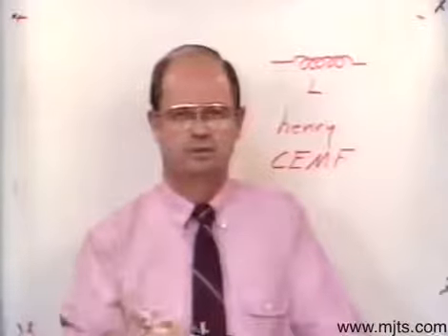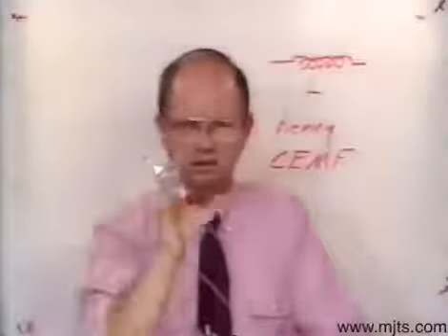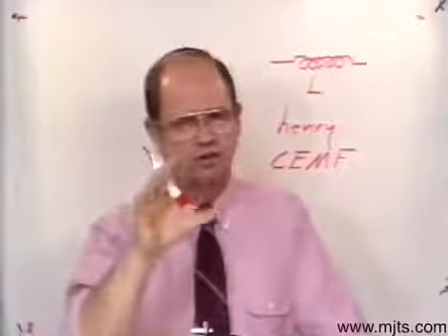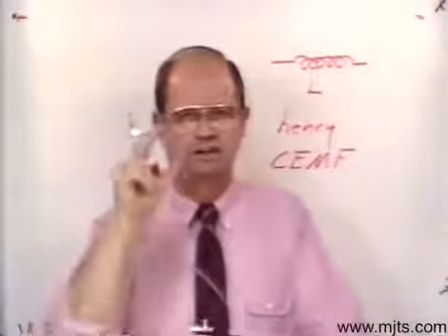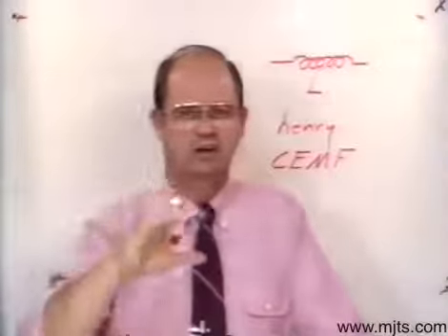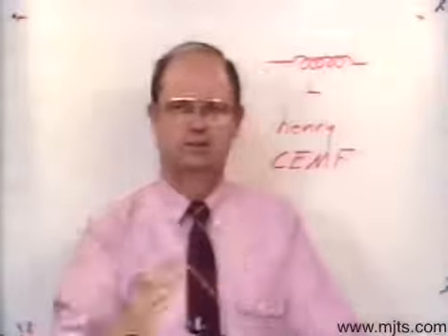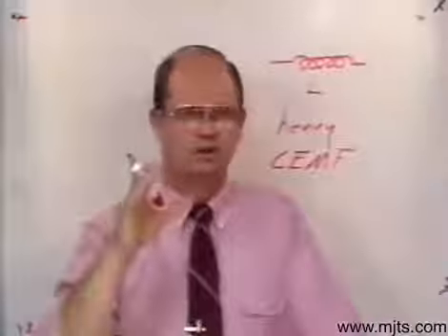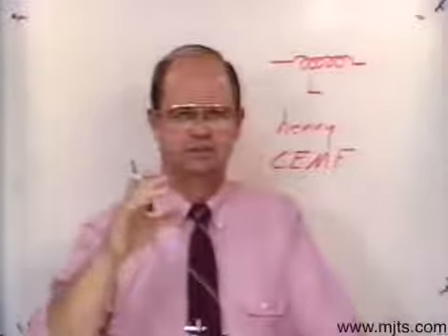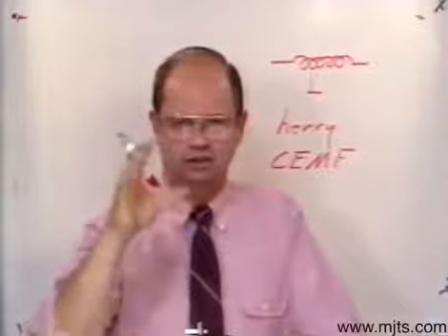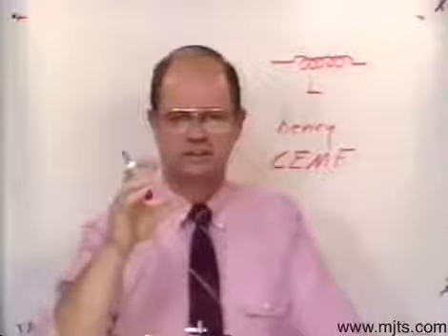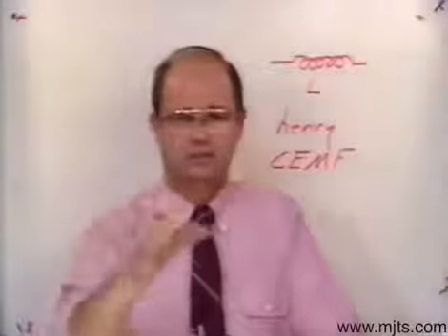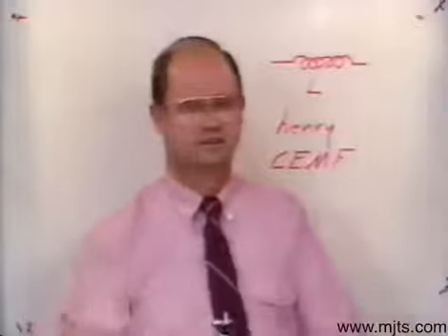The thing to remember is that a coil or an inductor, a transformer has a coil to it. Those coils oppose any change in the current flow, and the way they do it is by creating a counter electromotive force back on itself, or back voltage sometimes it's referred to. Now, if there is no changing magnetic field, then there is no opposition to that current flow in the form of that inductor. The resistance of the wire would be the only opposition to current flow if there's no change in the current flow. That's important to remember.